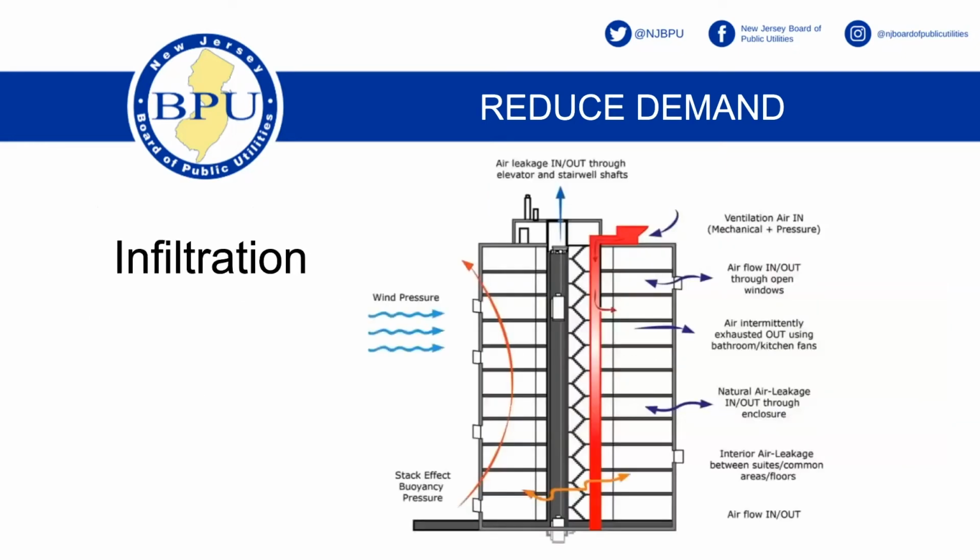Yeah. So here's kind of a little bit of a schematic, if you will, of how energy, heat moves throughout buildings. They have wind pressure. When you get wind, that increases the amount of infiltration, right? On the windward side, anyway. Stack effect is, you know, in these tall buildings, that's a lot more energy and a lot more force, I guess you would call it, right?